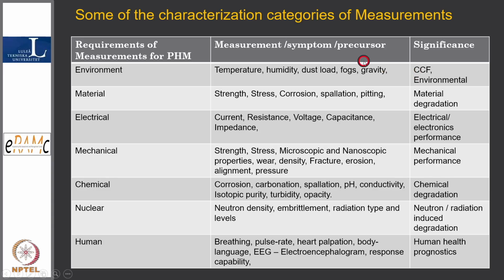It doesn't mean that the plants don't have any defense for common cause failure. A number of defenses are built in, but if you look at the safety assessment, common cause failure still requires a special evaluation because it has the potential to kill the redundancy. Diversity maybe not to that extent, but there are some common cause mechanisms like seismic loads. Seismic loads can couple one safety system to another safety system performing the same function. So that is the importance of environment.